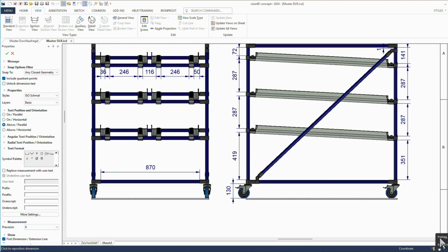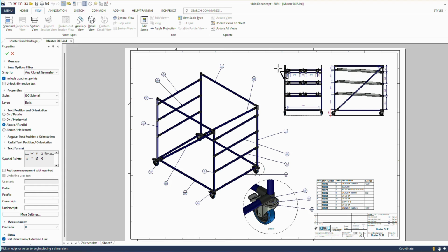Right, now we've got a complete overview. I think with a measurement like that, where I've marked it, you can set up the entrance structure quite easily. Now that we've drawn up the drawings, the next step would be to save the drawing sheet as a PDF file. To do this, we also have the Export Drawing Sheet button up here in the Quick Access toolbar. If I left click on it, then my File Explorer pops up and I can save it.